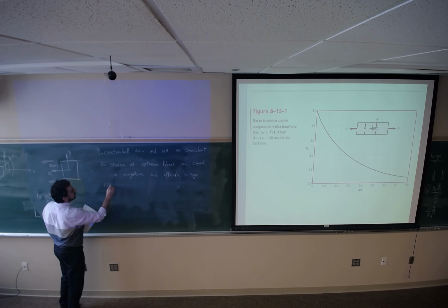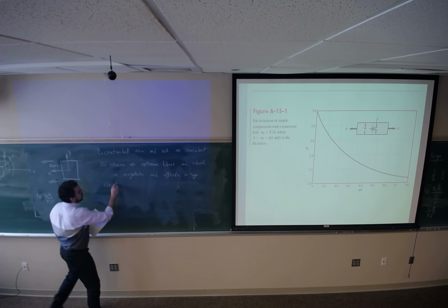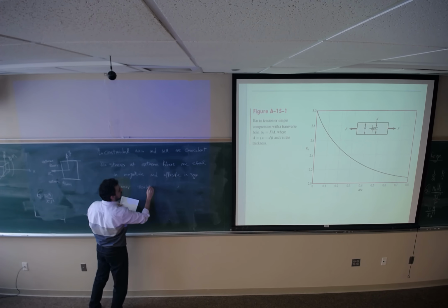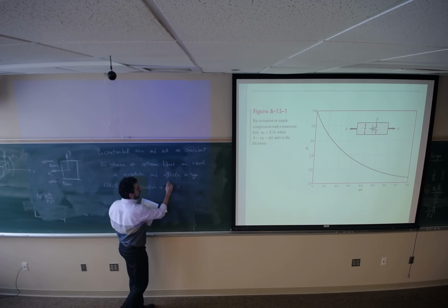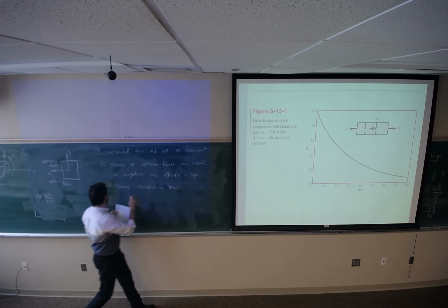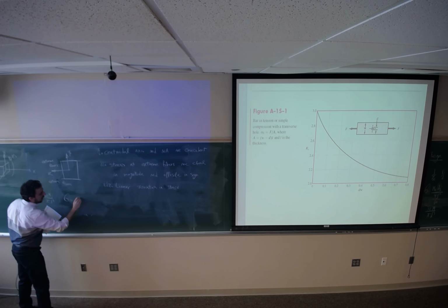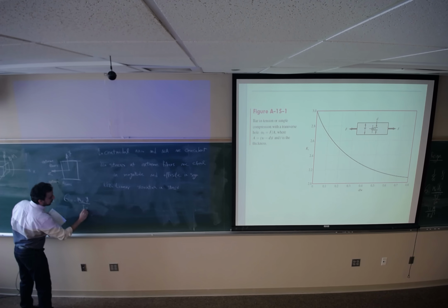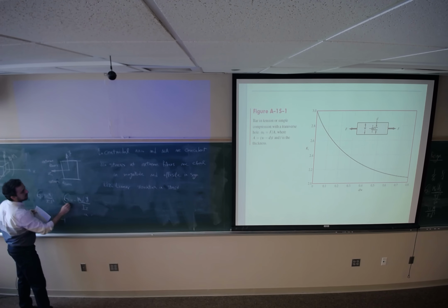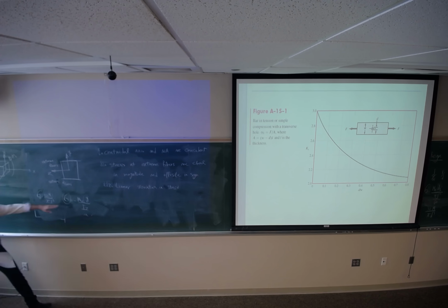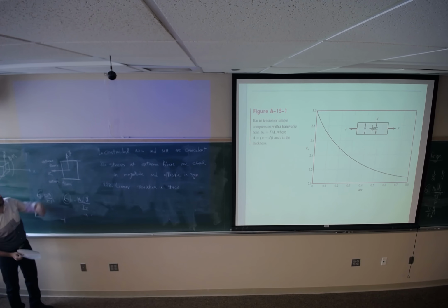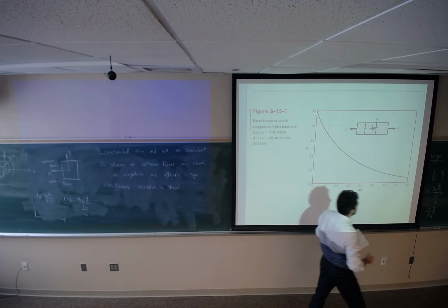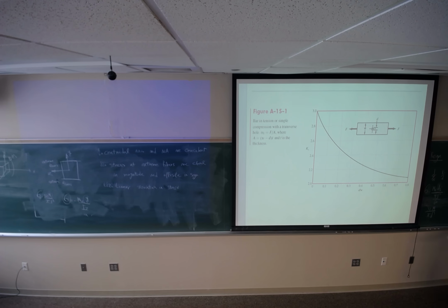And three, linear variation in stress. Sigma is Mz, for example, y divided by Iz. So the normal stress is varying linearly with the y distance from the neutral axis, if it's under Mz. So these are what we know about the straight beams.